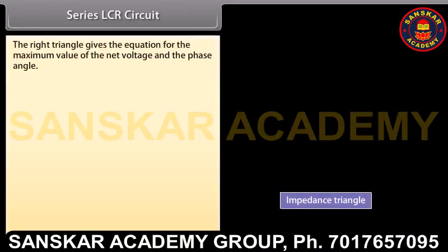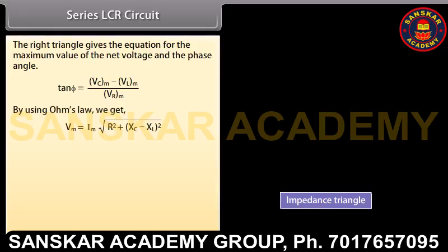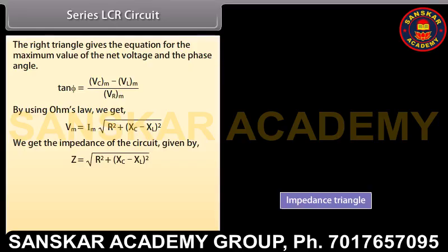The right triangle gives the equation for the maximum value of the net voltage and the phase angle. Tan phi is equal to (VCm minus VLm) upon VRm. By using Ohm's law, we get Vm = Im multiplied by under root of R square plus (XC minus XL) square. We get the impedance of the circuit given by under root of R square plus (XC minus XL) square.